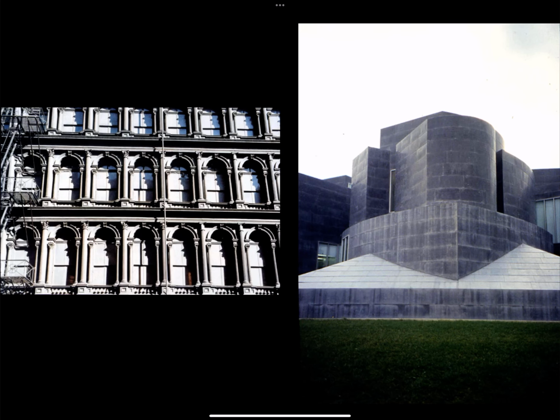So historically, the trend has been to reduce the amount of metal used to make the building envelope. The reason for this is we want to use less metal in order to reduce the cost. Reducing the cost not only of the cladding itself, but of all of the supporting structure behind. The less weight we have, the less structure required. And so to do this, ways have been developed of using thinner and thinner sheets of metal.